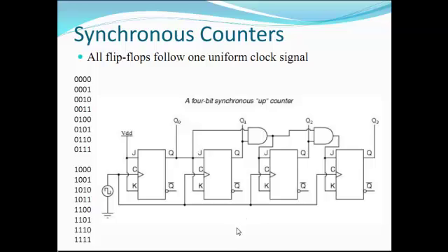This whole pattern follows all throughout as before, but these AND gates are extras to make sure that these inputs J and K are only true when these inputs are all 1. So in this example, when Q0 and Q1 are 1, then this AND gate outputs a 1 to this J and K, thereby inverting Q2.